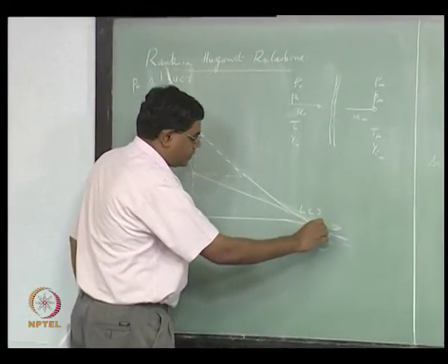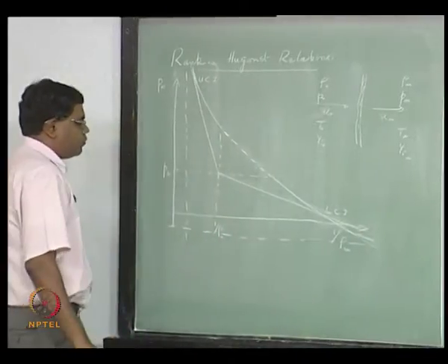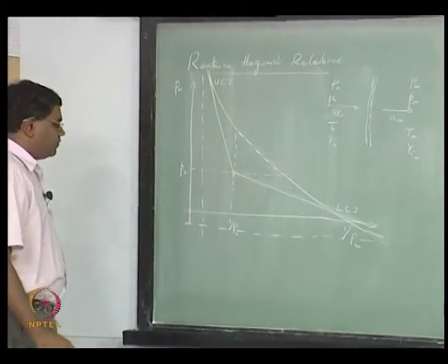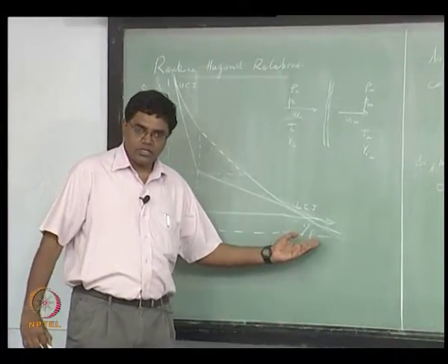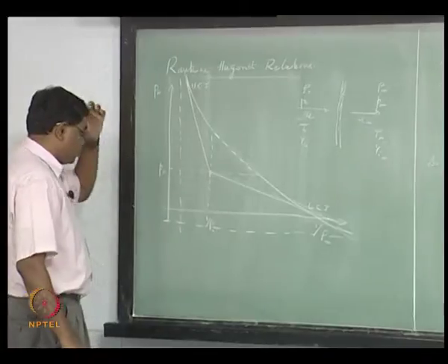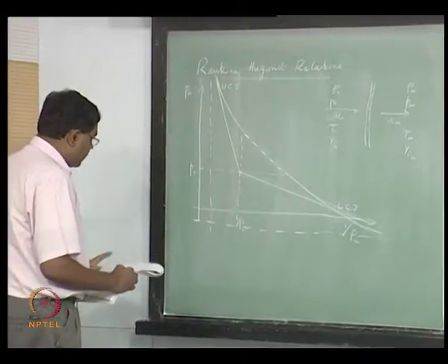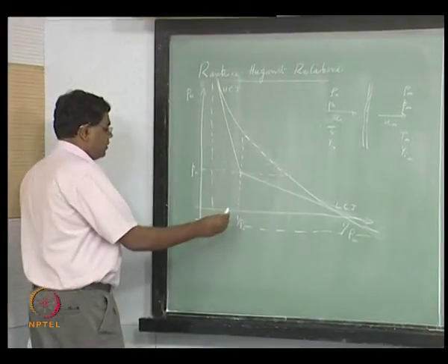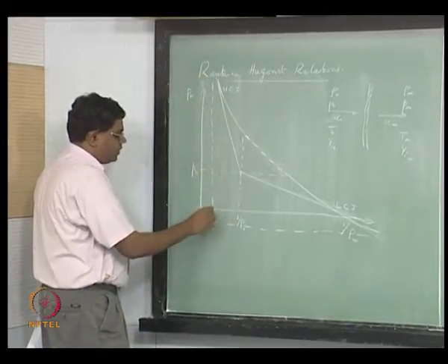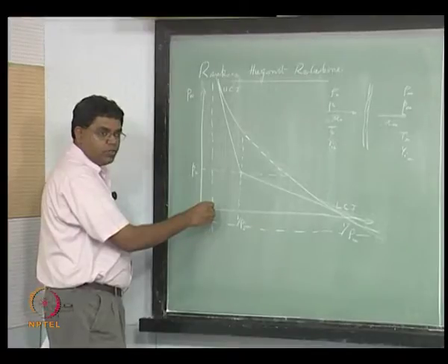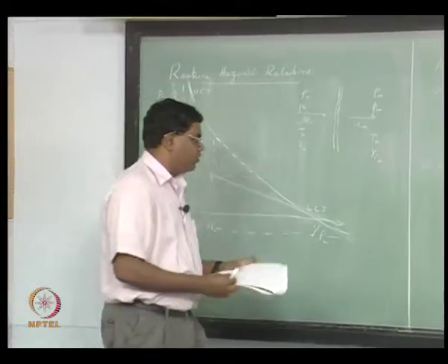Therefore this is your uppermost value of 1 over rho infinity. You can find that by plugging in p infinity equal to 0 in the Rankine-Hugoniot relation, and then solving for 1 over rho infinity to get an expression. The lowest value is when p infinity becomes infinity, which corresponds to the value of the asymptote, right?